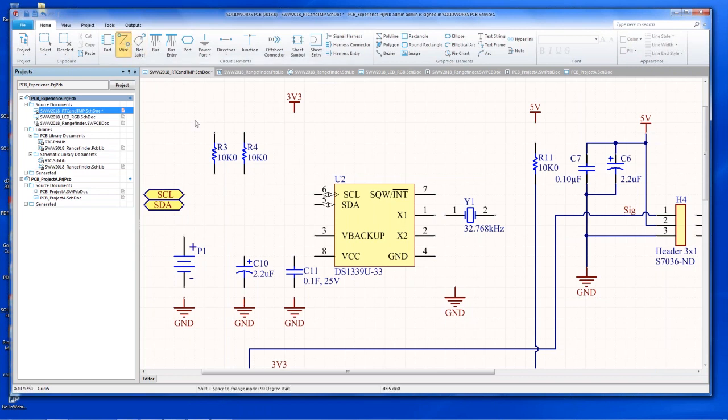So we'll just go to the wire command. Now we're in the wire mode. When we highlight and hover over an active pin, our cursor turns red. So I'll just quickly get this schematic wired up, and then we'll associate this to the PCB. Again, I'm continuing in the wire mode. SolidWorks PCB is smart enough to know when I end connections and when I can move to a new connection.